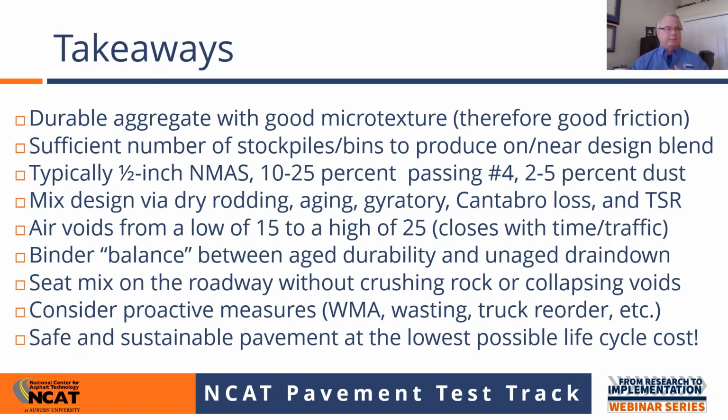And I know, again, from Florida projects, if they're paving at night and a truck gets held up and delayed, maybe the paver cools down. Maybe the mix has got cold clumps in it, but low mix temperature is a killer for open graded mixes, particularly when you're paving.